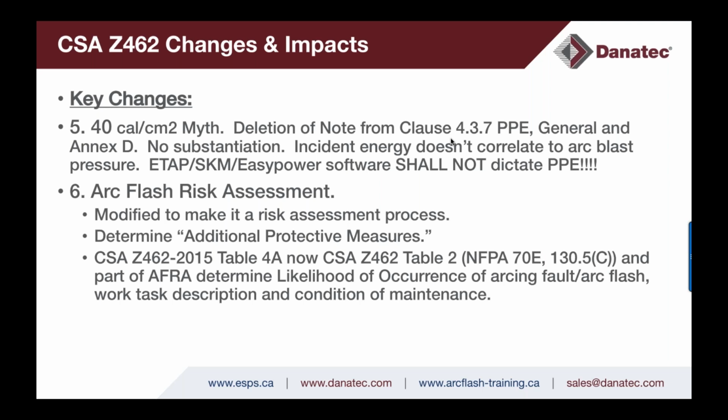It needs to go away, and it's going to be a challenge. I'll be continuing to promote this in future webinars and in presentations I provide to industry at conferences and workshops. There's also a miscommunication, a separate sidebar here, that operating energized electrical equipment is inherently an arc flash risk, and it's not. I'll probably discuss that in more detail in the risk assessment procedure part 2 webinar. This was also propagated by the software tools, including PPE in the results tables, and unfortunately they still do include PPE in the results tables.